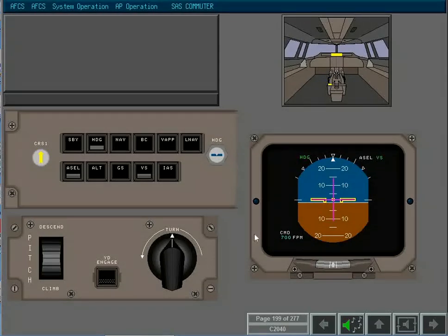You will recall that the vertical speed command from the flight director pitch bar can be adjusted either through touch control steering or autopilot pitch wheel movement. Use the autopilot pitch wheel to adjust the vertical speed to 1000 feet per minute climb. The pitch control wheel can be used to reset the pitch datum in vertical speed mode and IAS mode. Pitch wheel signals and turn knob signals are inhibited after glide slope capture.